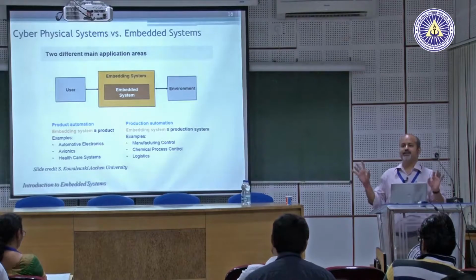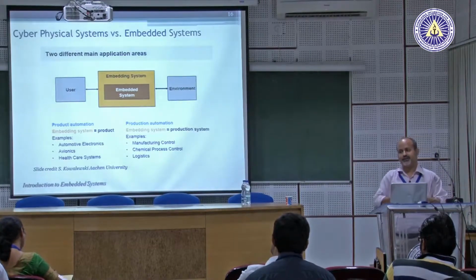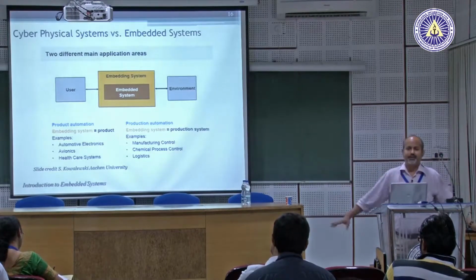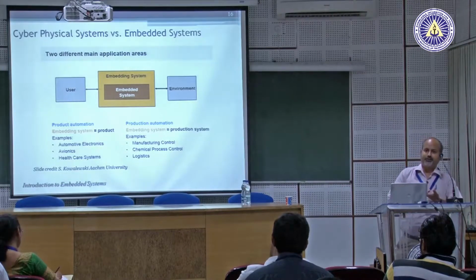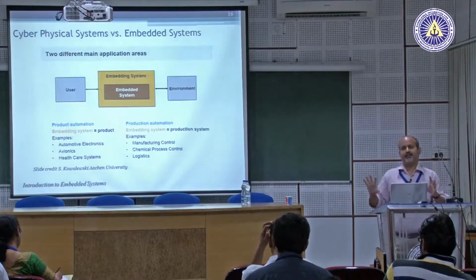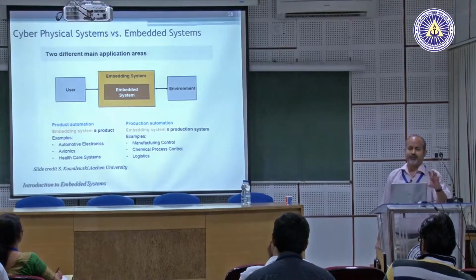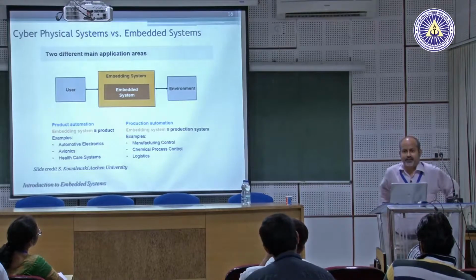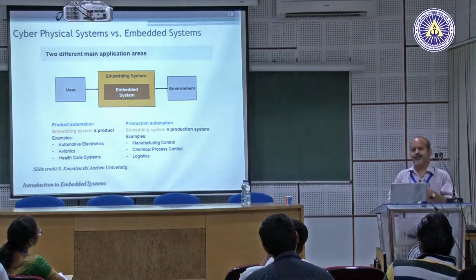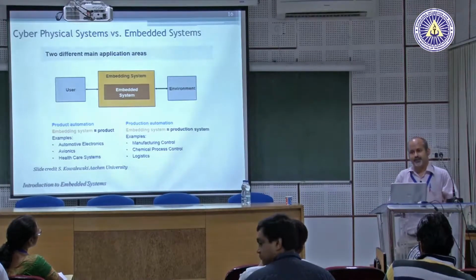A human engineer sits at the control center. If you ever visit a control center, you'll see a lot of displays, and they are looking at them. All the sensor data is being converted into knowledge and displayed on these displays, and these engineers can then make a decision: we have to do load shedding here, or generation shedding here, or we have to call this person and say their reactive power is not being supported and they have to do something, or I have to start pumping in some power here.